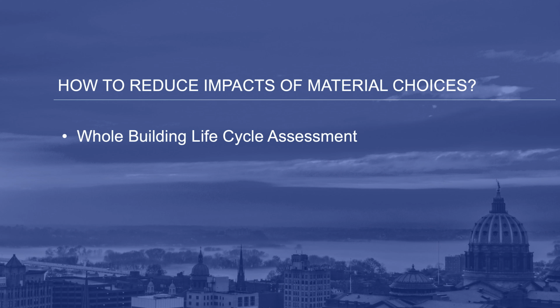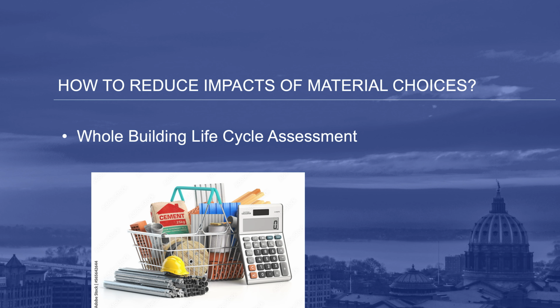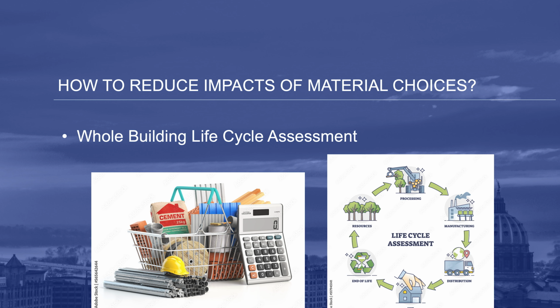Number 1, ask your team to provide a whole building life cycle assessment. Life cycle assessments, LCAs, and life cycle inventories, LCIs, are methods of investigating, quantifying, and documenting the environmental impacts of a product for each stage in the life cycle. A whole building LCA looks at all the materials planned for use in that building to give you, the client, the ability to understand the impacts of the materials chosen for that building on the environment, determine if there are impacts that can be mitigated or replaced, and communicate about your decisions.